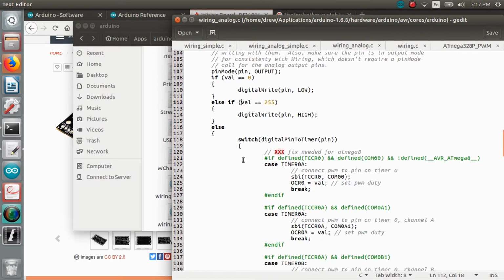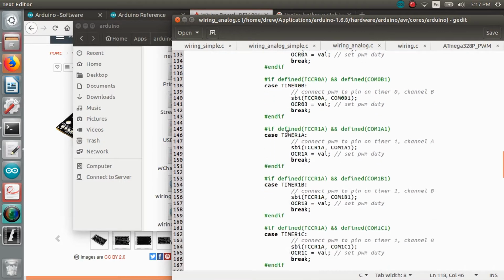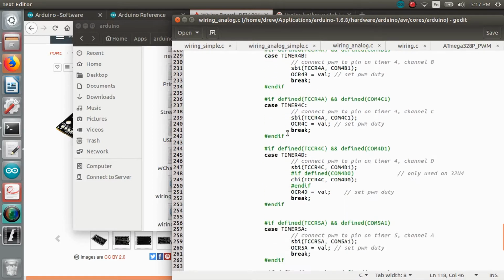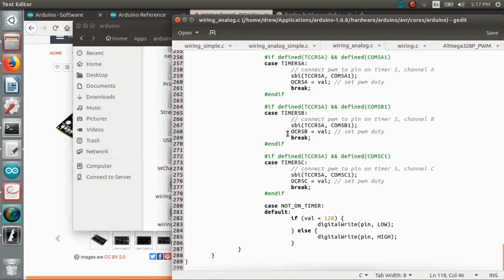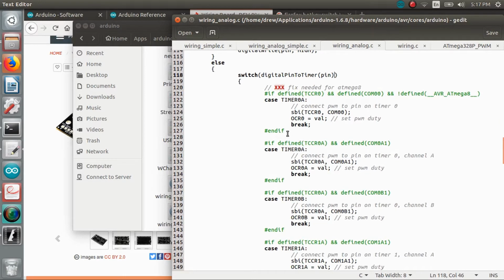So far so good, but now it gets interesting. A helper function determines which timer module the pin argument corresponds with. The rest of the function is one enormous switch case statement that contains nearly 20 identical cases. Only one will run depending on the selected timer.